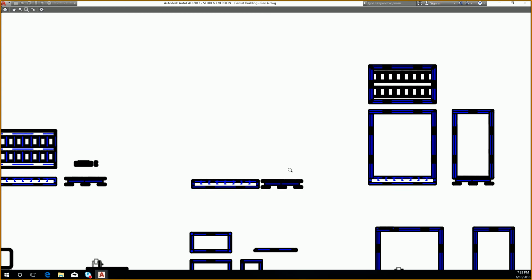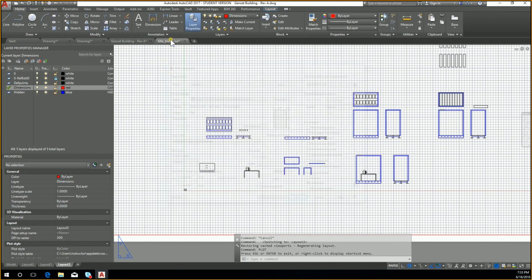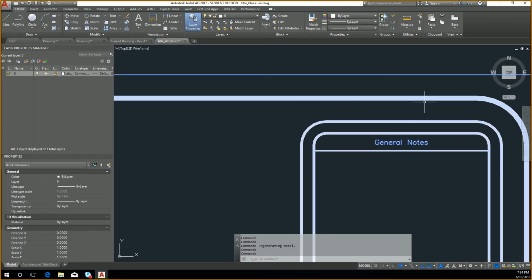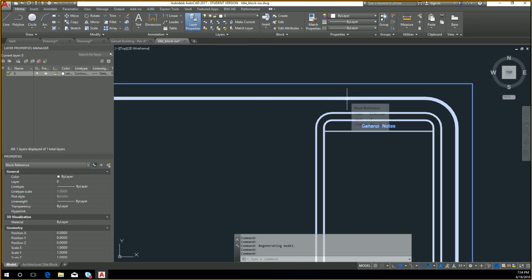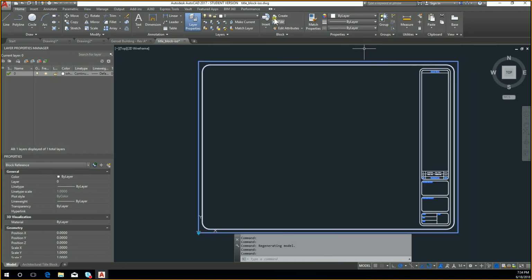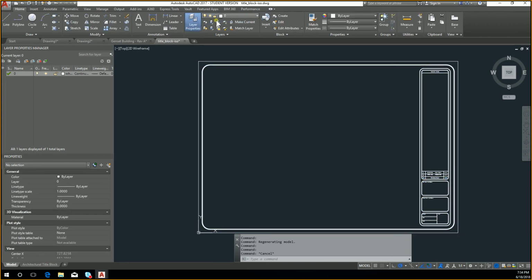Usually it's borders, just like this. You do not actually have to have it drawn thicker in your model space. You can handle that all through your layer control. So that could be on a thicker layer through here. Instead of everything being layer 0, you can create layers that are border layers that are 2 mil thick.